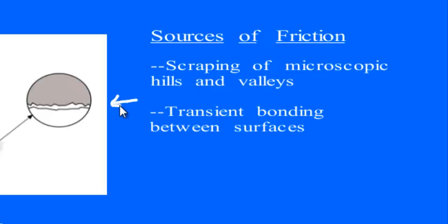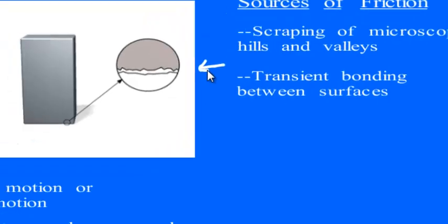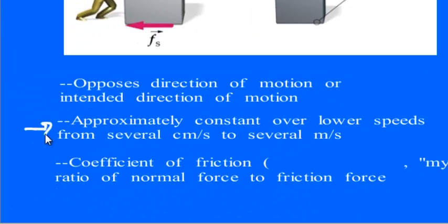It's actually fairly complex, but we found some basic ways to simplify it, and that's because of the following. If you look at the other part of the screen here, it turns out that despite the complicated nature of the friction force and all the things that are interacting to cause it, over a pretty wide range of speeds the friction force is constant. In other words, it's not velocity dependent. That's going to vastly simplify the equation that we use to model the friction force.